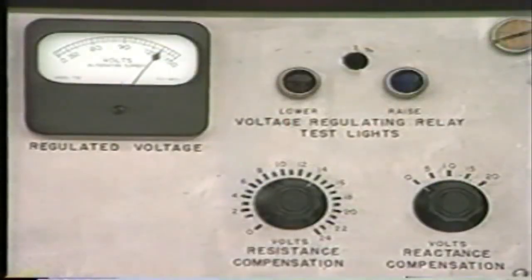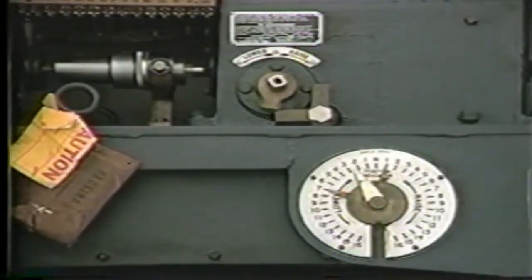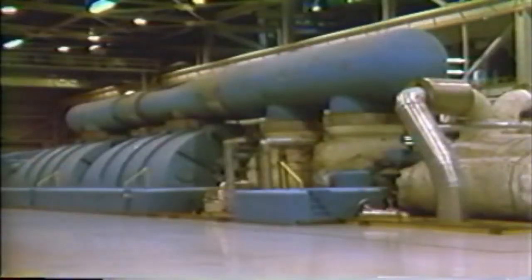However, there are other relays installed on the system which do not cause tripping of breakers for protection. But a knowledge of these relays is important in operating and maintaining the power system. One such classification is that of regulating relay. A typical example is the type of relay used to change the taps on a transformer. Another regulating relay is that used to adjust the governor set point on generating equipment and so control the power output.